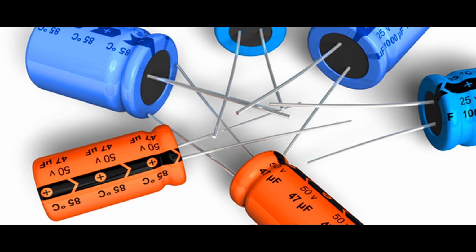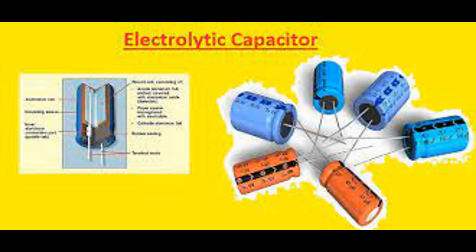Advantages of capacitors in energy conversion. Fast response. Capacitors can charge and discharge quickly, making them suitable for applications requiring rapid energy transfer. High power density. Supercapacitors provide high power densities for applications needing bursts of energy. Versatility. Capacitors can be used in various energy conversion scenarios, from touchscreens and imaging to power factor correction and energy storage.